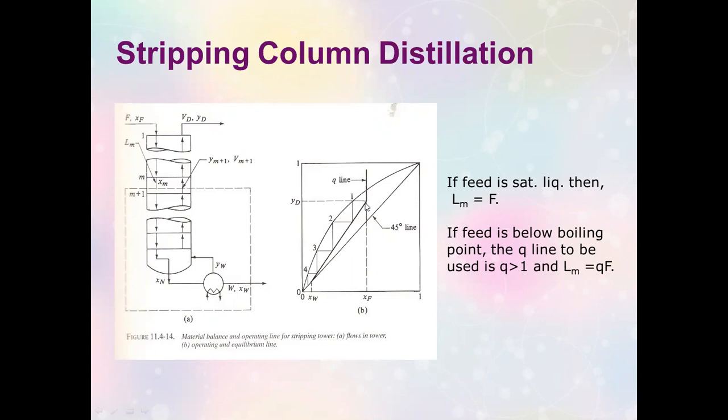So what would you do with the corresponding value of the distillate mole fraction? On the vertical axis, if you're doing it graphically, project that right onto your q line, which is vertical. You simply go to the right and end there on the q line that you have drawn. You have xW here, which is the beginning of the stripping section operating line.